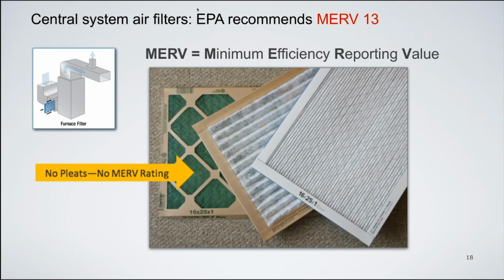These sometimes in ancient days used to be made out of rubberized horsehair, and now they're typically made out of polyester. But they're designed principally for protecting equipment, making sure that the cooling or the heating equipment doesn't get clogged and gummed up with filters. These type of filters are available. They're very inexpensive. They don't have any MERV rating because they take very little in the way of larger or smaller particles out. They're for feathers, very large things.